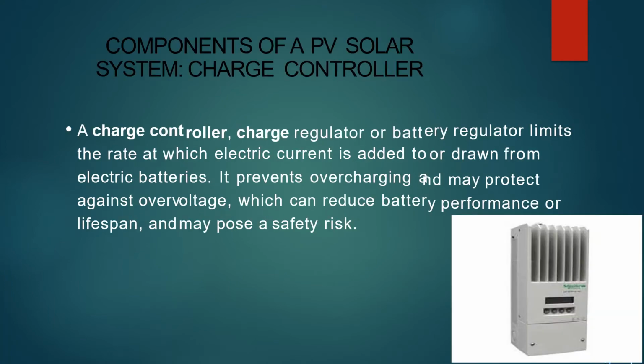The third component is the charge controller. A charge controller, or charge regulator or battery regulator, limits the rate at which electric current is added to or drawn from electric batteries. Actually, it regulates the voltage and current coming from the solar panels going to the battery.